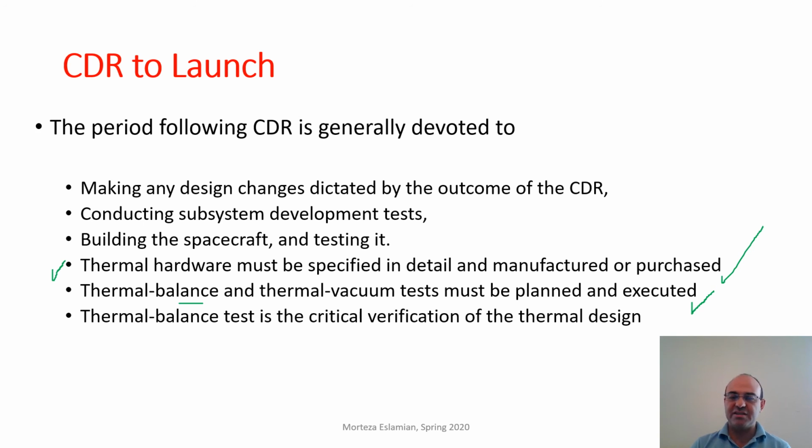That's for the components. And then the thermal balance test will show that when all of these subsystems interact with one another, they are thermally balanced, meaning that it will show that the thermal solution is adequate and can actually manage the corner cases.